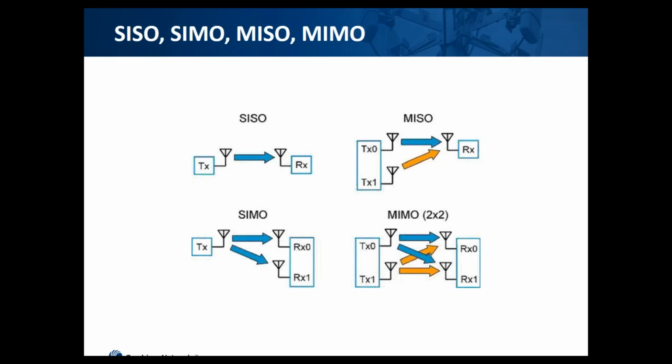One way is to physically separate the two antennas. If they are spaced far enough, the path the signal takes from the transmitter to each of the receivers is different, and the received signals will also be different. How far apart do we need to place them? How far is far enough? This depends on the wavelength and the frequency. As a rule of thumb, we want to place the antennas a wavelength apart. This means that the higher the frequency, the closer the antennas can be. But if the frequency is lower, we need to space them more to achieve the same effect.